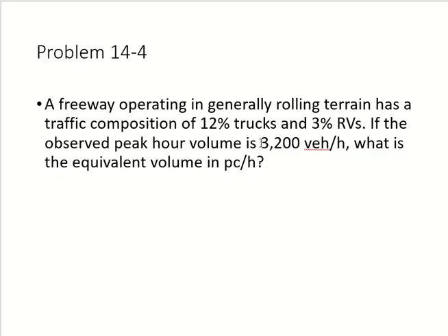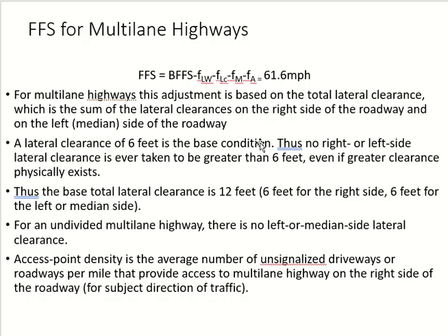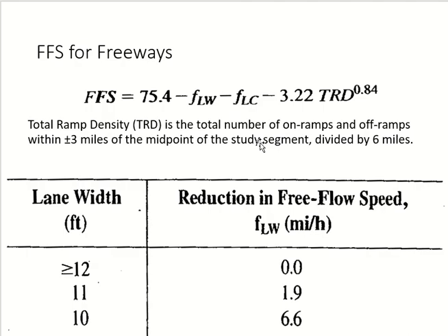It's a freeway example. Okay, FLW is what? Factor for lane width. Okay, we have a table for it, right? You can see the table on the slide.